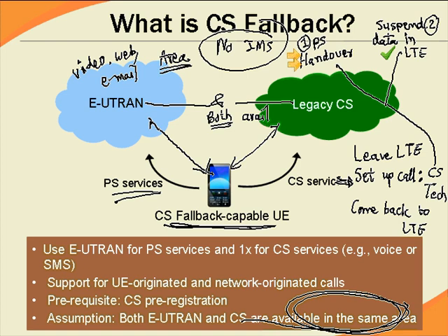Now, there is a question on dual receiver UE. Here is the problem. If you want simultaneous voice and data, because that's your basic question, can we have a voice call on CS and data on LTE? Yes, it is possible if the UE has dual transceiver, meaning transmitter and receiver. You cannot have just a dual receiver and have data sessions ongoing along with your voice call.